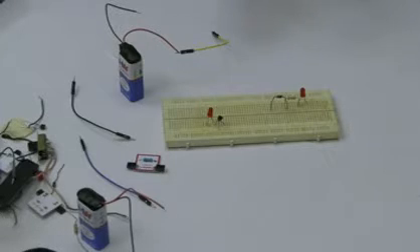So you just key in the number on your transistor on a Google search and you would get the pins of your transistor. So for the transistor we are using, this pin is the emitter. The pin in the middle is the base and the last end is the collector.